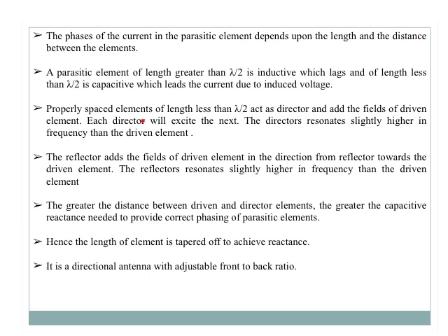Now the properly spaced elements of length less than lambda by 2 act as a director and add the fields of a driven element. Each director will excite the next. The directors resonate slightly higher in frequency than the driven element. The reflector adds the fields of the driven element in the direction from reflector towards the driven element. The reflectors resonate slightly higher in frequency than the driven element.